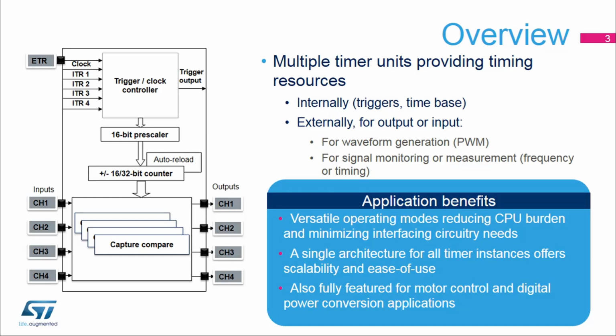The software tasks mainly consist of providing time bases, timeout event generation, and time triggers. The hardware tasks are related to I/Os. The timers can generate waveforms on their outputs, measure incoming signal parameters, and react to external events on their inputs. The STM32 timers are very versatile and provide multiple operating modes to offload the CPU from repetitive and time-critical tasks, while minimizing interface circuitry needs.